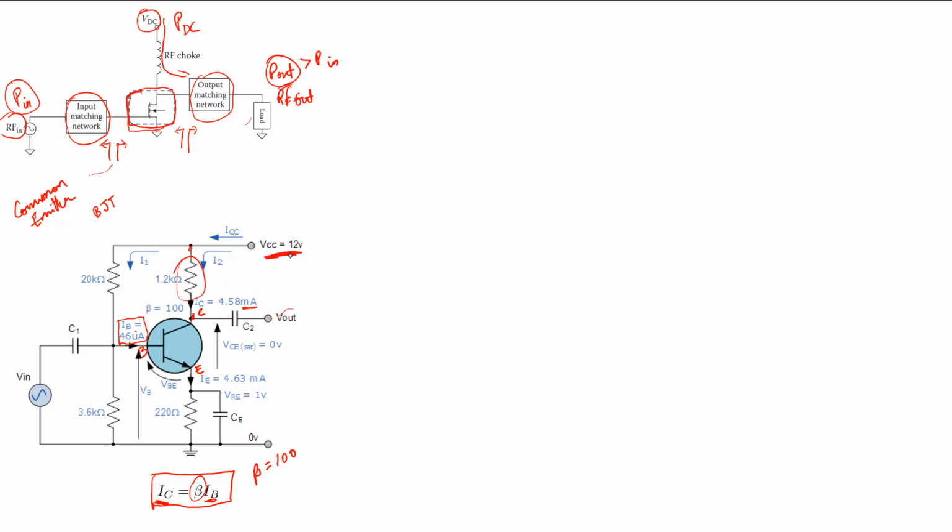So this supply voltage is going to be providing what is called the DC bias for this amplifier through this kind of a resistive divider network, which sets the base current when there is no RF signal, when the amplitude of the input signal is 0. What the base current flowing in should be is determined by these resistors here.